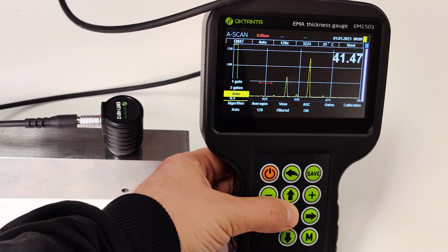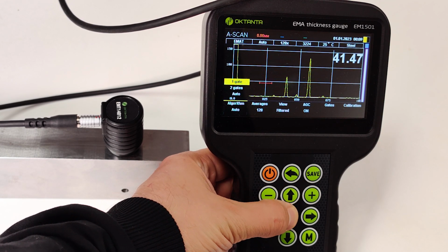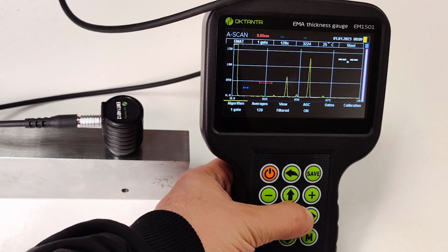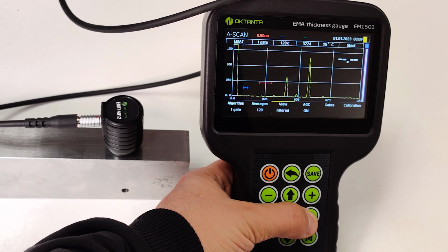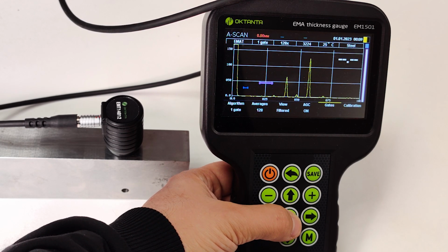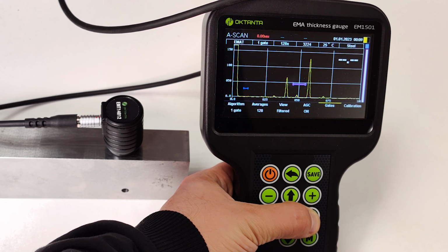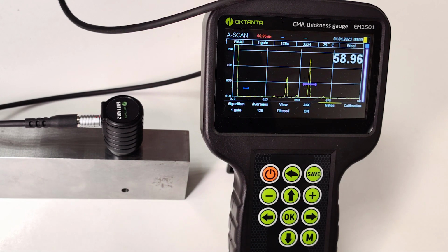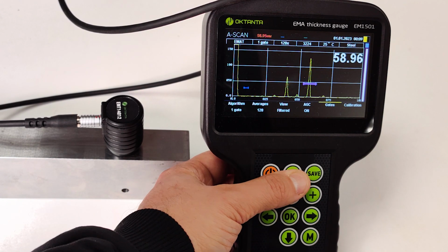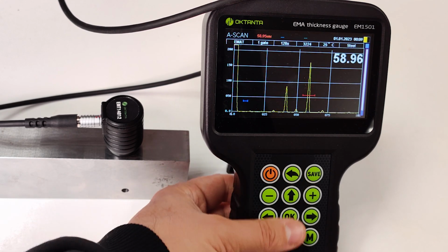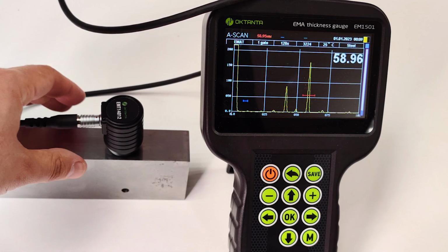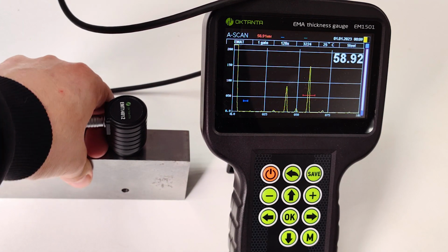In the area of the hole, there is both a signal from the hole and a signal from the opposite surface on the A-scan. Of course, the device does not have information about what exactly we are measuring and displays the minimum thickness. In this case, the manual measuring mode will come useful again. This time we will use 1-gate mode. Let's place the first gate in the area of the bottom signal. The device now takes into account only the signal in the zone limited by the gate, therefore it does not react to the echo signal from the hole.